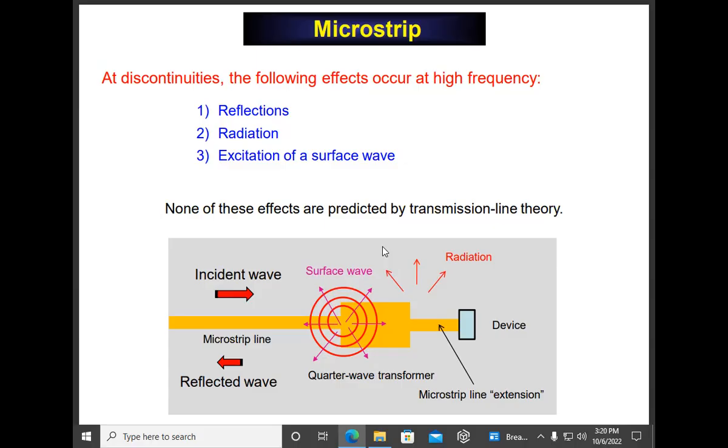But in the electronics world, another use of transformers is to transform impedance. If the turns ratio of a transformer is called N, N to 1, primary to secondary, then of course you have a voltage transformation ratio of N, but the impedance transformation ratio will be like N squared. So any transformer can be used in two ways: to transform voltage or to transform impedance. Again, the power world uses them to transform voltage. The electronics world really uses both. Sometimes we use it to transform impedances. But anyway, this is what we're doing here.